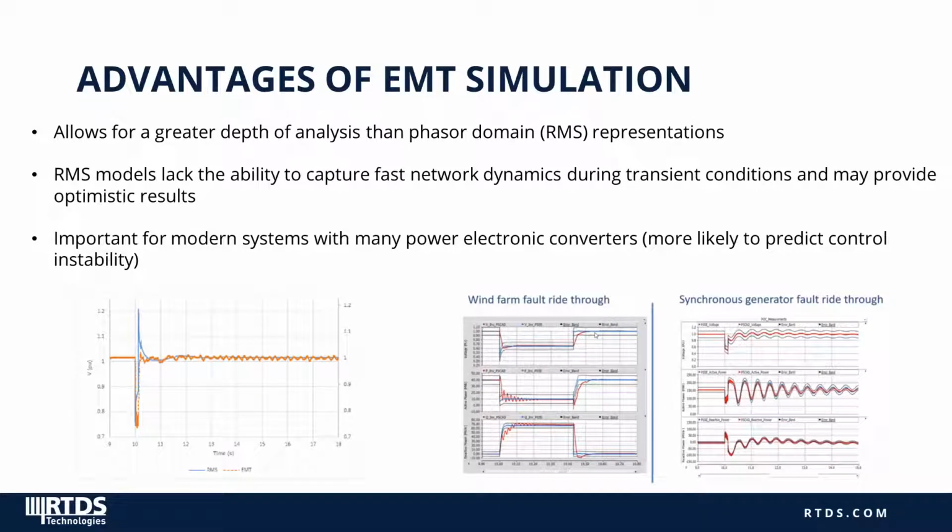In the images on this slide comparing the results of RMS and EMT simulations, the EMT simulations are capturing some dynamic behaviors that are not visible using traditional simulation. And being able to capture those deviations is very key for identifying and mitigating vulnerabilities in the DER-heavy modern grid.